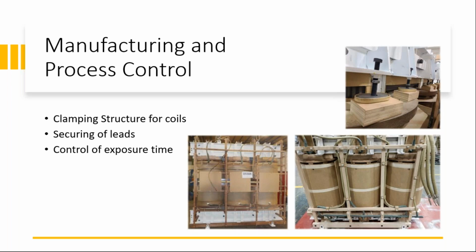If one or other lead gets detached from the cleats, it could end up getting away from the supporting structure and reduce the clearance, and the job may not fail from short circuit forces, but it could have damage from electric failure. So all those things add on to the precautions we take as the transformer is being manufactured.